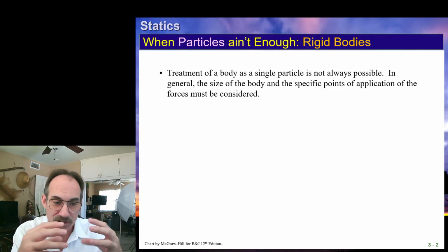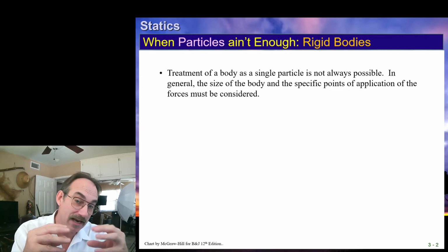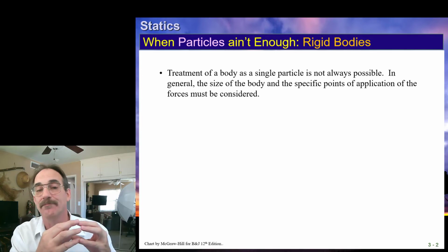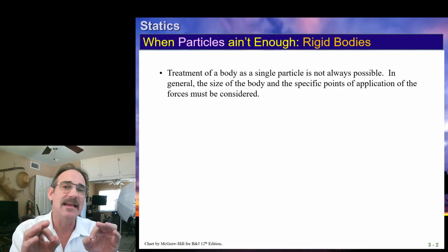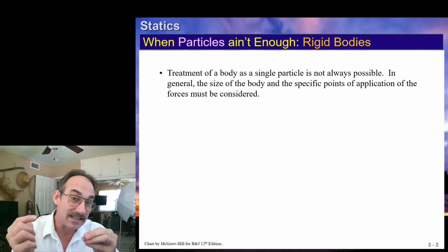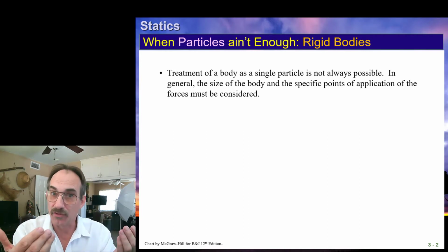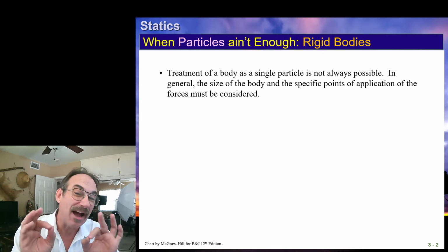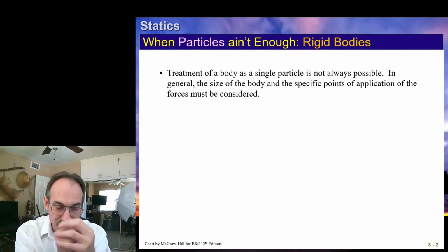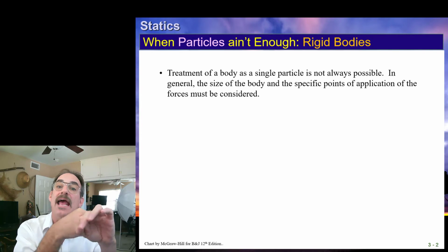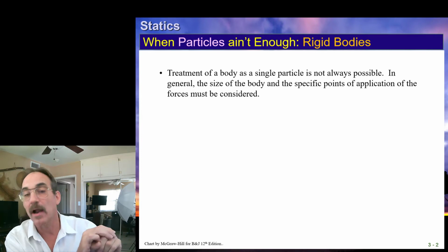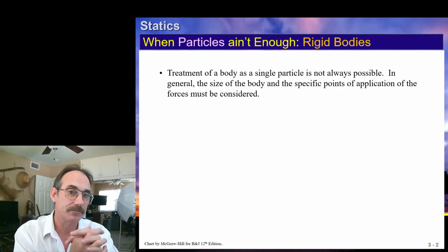To calculate the basic forces on the aircraft and what its acceleration is based on the resultant thrust and lift forces, we often can do a lot of the early analysis treating that aircraft as a particle, just squishing it together and looking at what the net forces are and what the acceleration, directions and velocities are as a result of those forces.